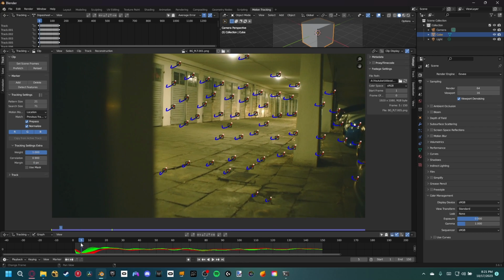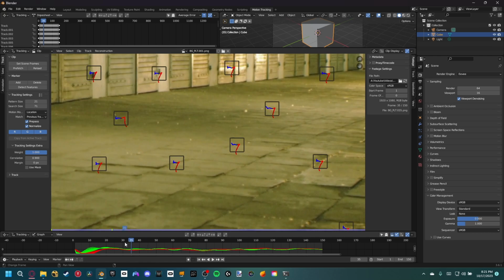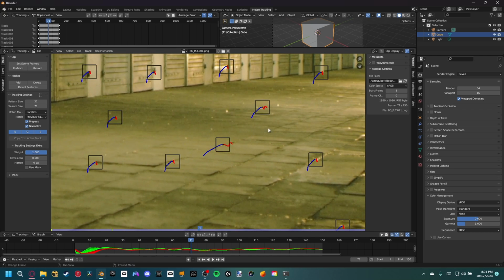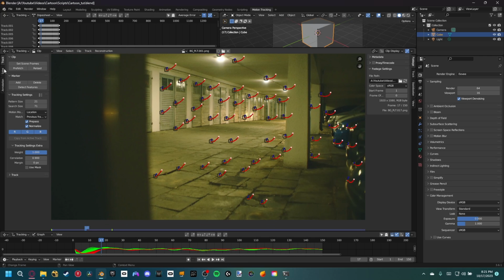Then let's do a more visual pass up here. Let's scroll throughout our clip, and you just want to select any points that move around. You'll notice if I zoom in here, these 2 points are stuck on these moving particles down here. So I just want to go ahead and find all of those and delete them. Okay, so once you're happy with that, let's go and get a camera solve.